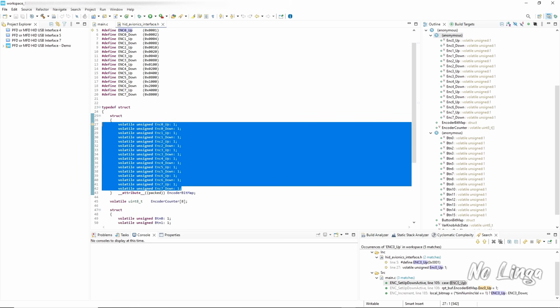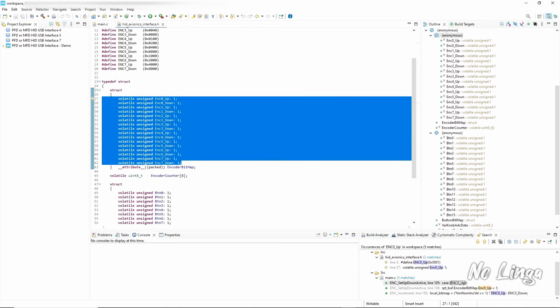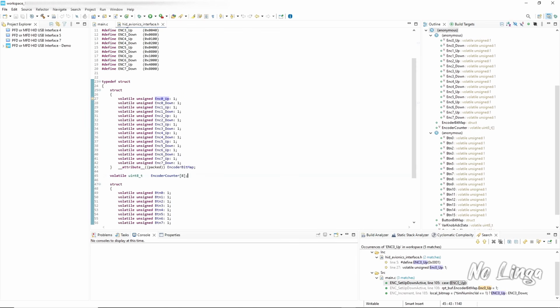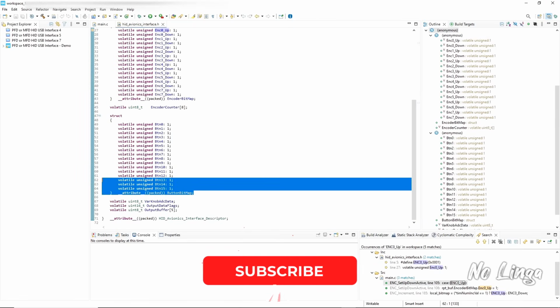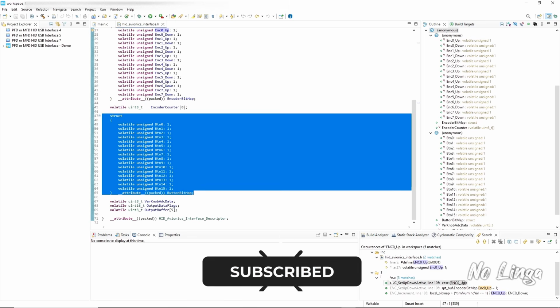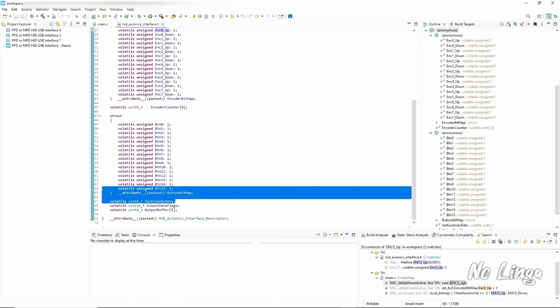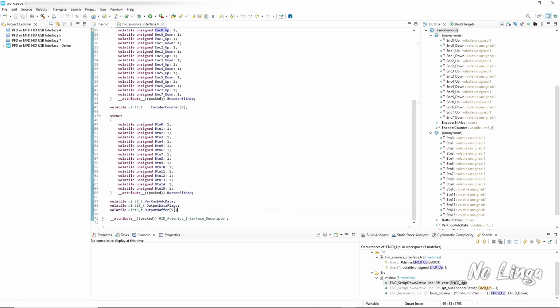The first 16 bits represent the first 2 bytes of the structure. These additional 8 bytes add up to 10 bytes. And then these 16 bits, there is an additional 2 bytes, and then another byte. These are all input. Input meaning what we're sending into the computer with the HID descriptor into the flight simulator. And these are output. So we'll use this for PID functionality output. And we can expand this later. But just so you know, we're using this for output.